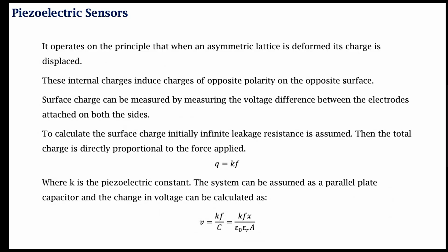Usually, the electronics that is used to interface it with the rest of the system can be considered as a resistance. So this is essentially an RC circuit. This essentially creates a high pass filter. This is an RC circuit that acts as a high pass filter.